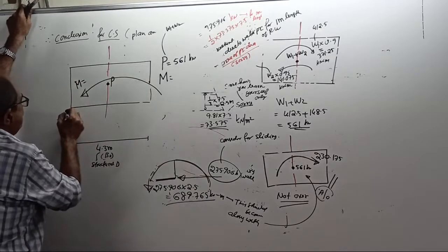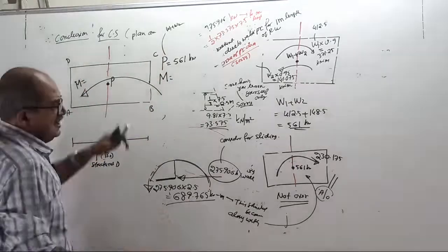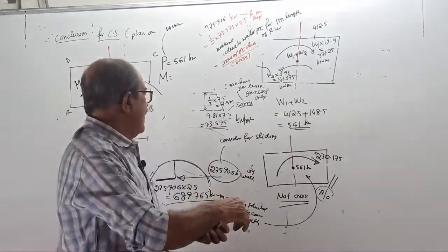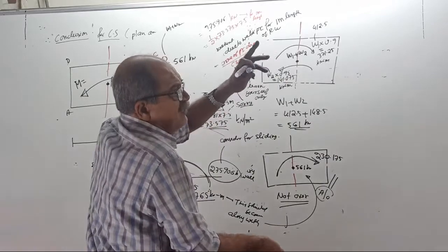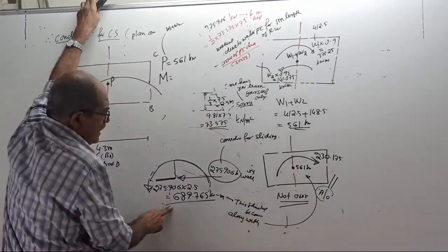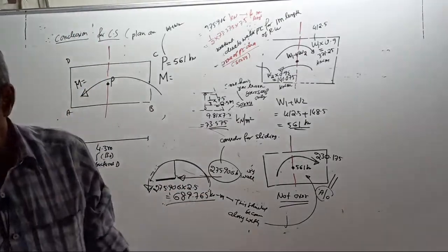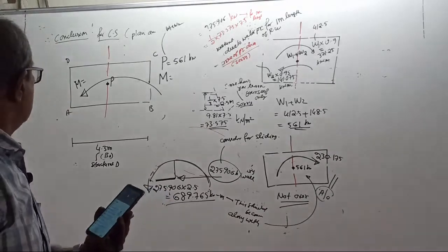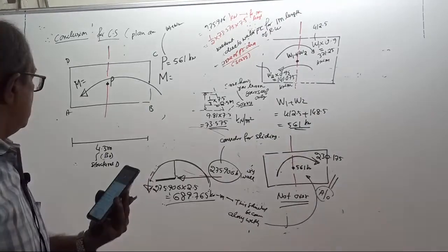I will call it ABCD. Okay, once again, back to square one. The moment due to masonry weight, the resultant is on that side, it is coming 230.175 that way. And water pressure will give a moment of 689.765 this way. Net answer, final answer, single moment.